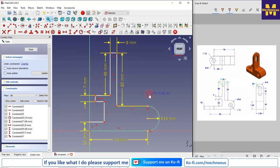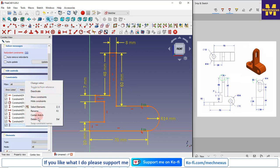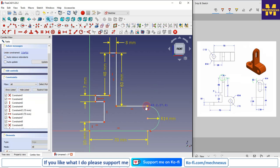Now there is a dimension which is missing, so we will find it from here. This should be vertical, and I will delete this constraint 32. So this is the 10 mm, this is the 7.